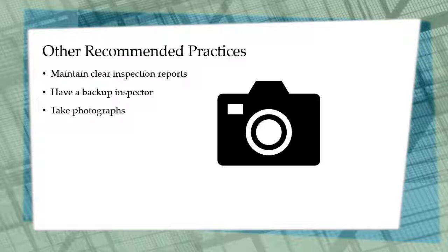Make sure that there's a backup inspector so that if you're not available, someone else will be able to follow up on any outstanding issues. And take photographs and include them in your inspection reports in case you're not around in the future and someone else needs to go out and complete the inspections for that project.